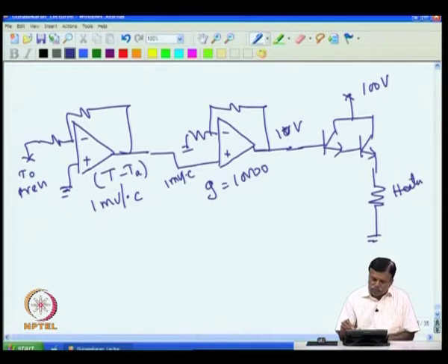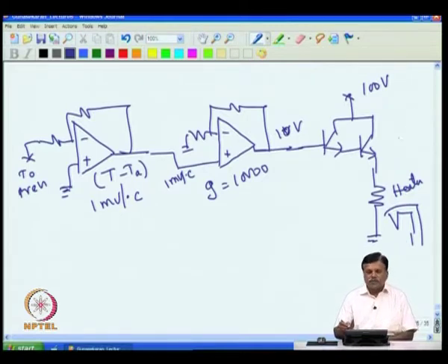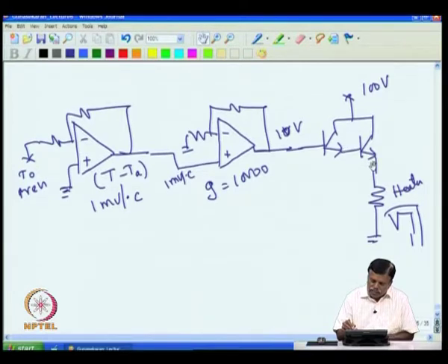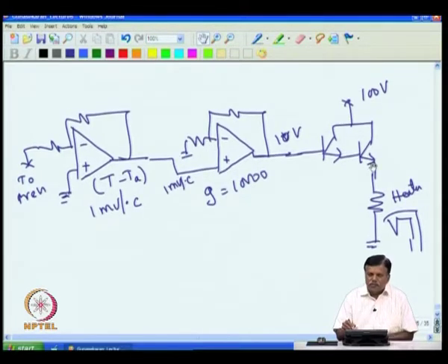This heater is in the oven, and only the thermocouple is kept to measure, as we had seen in the previous figure. The thermocouple is physically kept here to sense the temperature of the oven. Now if a 1 degree difference is there, you get 10 volt, and if the 10 volt is present here, you will get 9.4 volt at this point, and then another 0.6 less here,